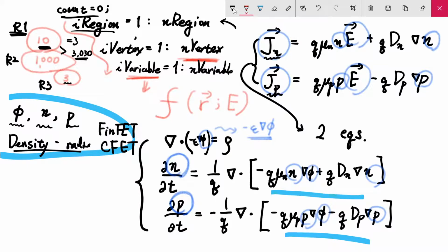Another example we can think of is trapped charge density. Maybe Mr. Bach is now dealing with this quantity, the number of traps. The number of trap sites can be really position dependent. For example, at a certain position we can have multiple trap levels, and at another position we have a different number of traps. So in implementation, we usually also have an internal index. It is not just a double precision number, but we can also have a trap index.